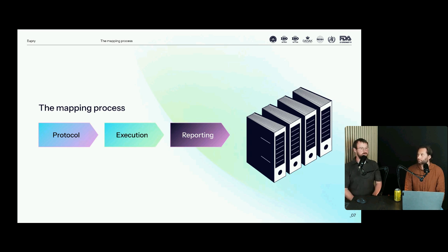So how did you perform risk assessments? Where did you choose to place data loggers? That's one of the questions we get every single time. How many data loggers should we place? But that should all be stated in the protocol together with the scope and the expected outcome and the acceptance levels. So those are some of the things we'll take a look at today as well.